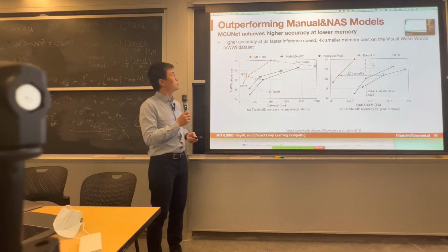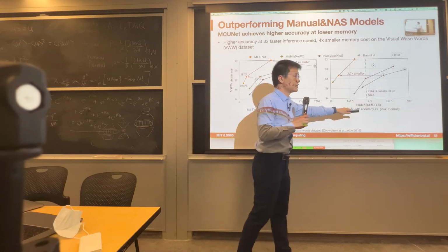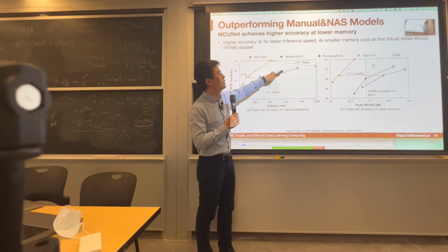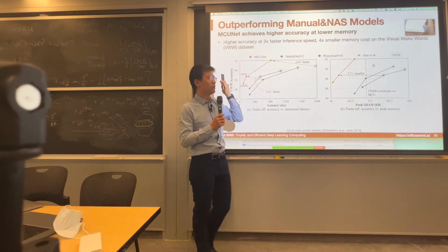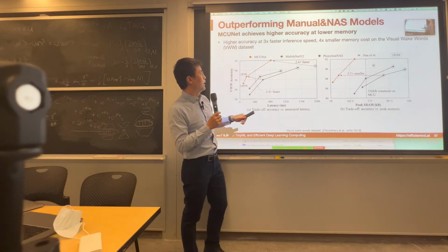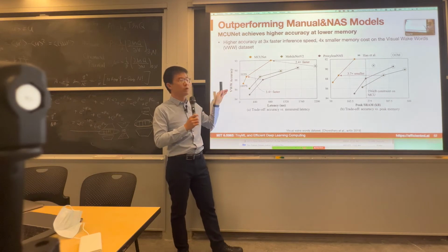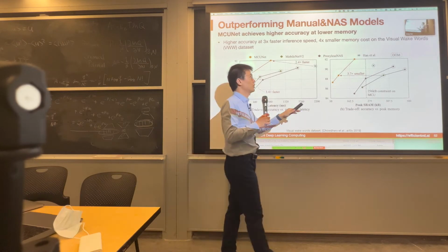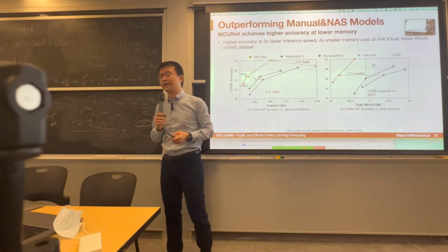So here I'm going to show some results. Okay, so MCUNet, this is the latency, and on the right-hand side is the peak SRAM usage. Several baselines: MobileNetV2 from Google, ProxylessNAS, which we described before, and this is our prior result in 2019 in the Low Power Computer Vision Challenge. By designing this TinyNAS, on this Visual Wake Words dataset, we can achieve 2.4 times faster model, requiring 3.7 times smaller amount of SRAM while maintaining the same accuracy.